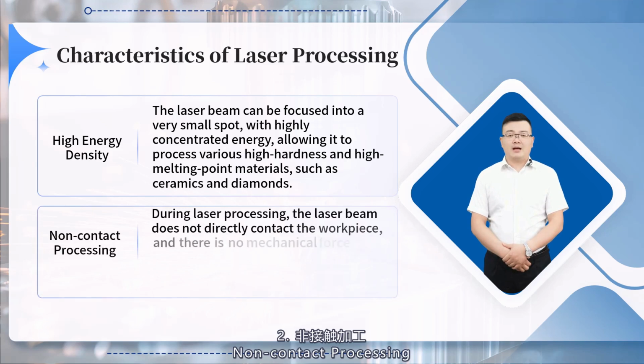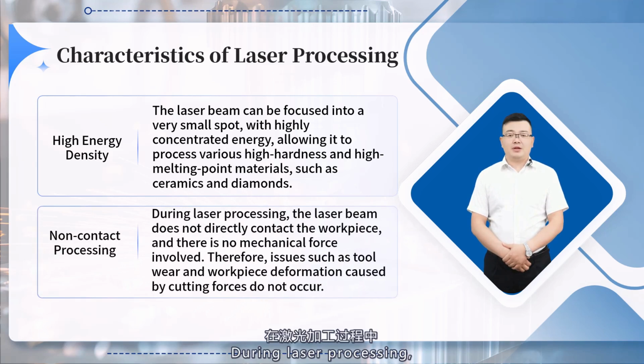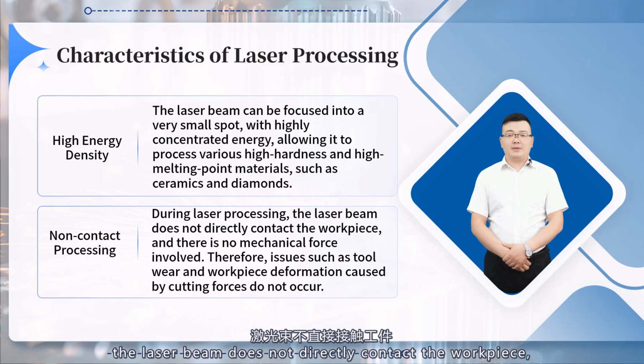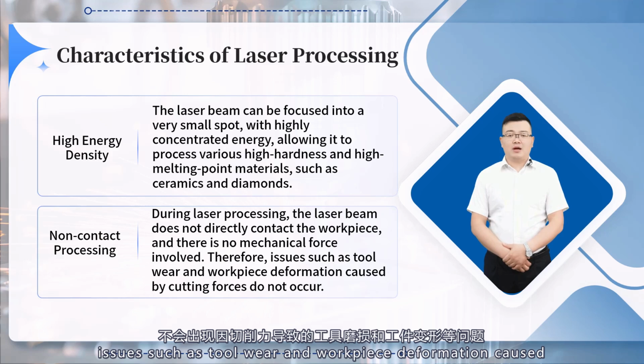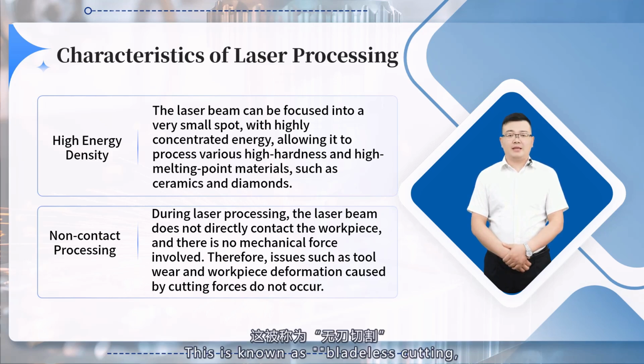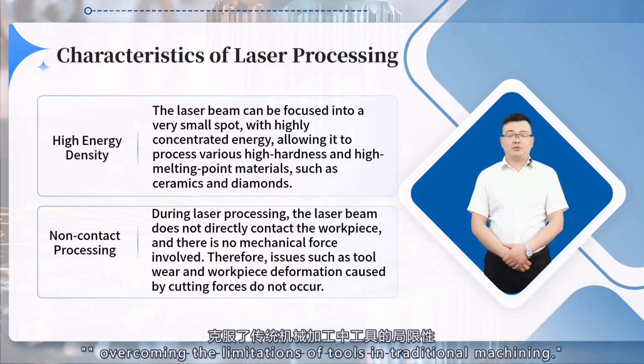2. Non-contact processing. During laser processing, the laser beam does not directly contact the workpiece, and there is no mechanical force involved. Therefore, issues such as tool wear and workpiece deformation caused by cutting forces do not occur. This is known as bladeless cutting, overcoming the limitations of tools in traditional machining.